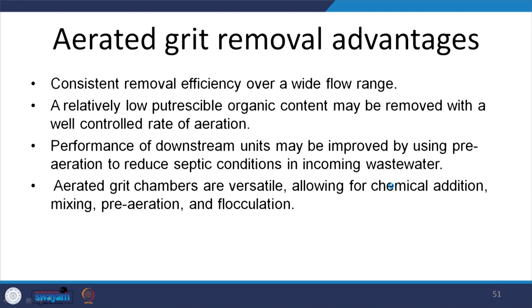So, what are the advantages? Let us just look at that. Over a wide flow range, you will have consistent removal efficiency, because it is mostly dependent upon the spiral action or the air that you are pumping in. So, some organic content may be removed with a well controlled rate of aeration. So, you can start organic degradation earlier, but obviously microbe concentration is less.